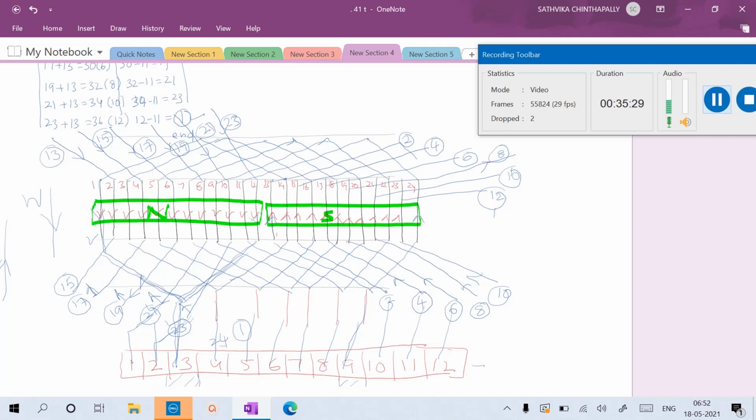After drawing the number of parallel conductors, draw all the conductors at a uniform distance and number each conductor at the top. Then, as per the winding table, connect the conductors on the back side and front side.